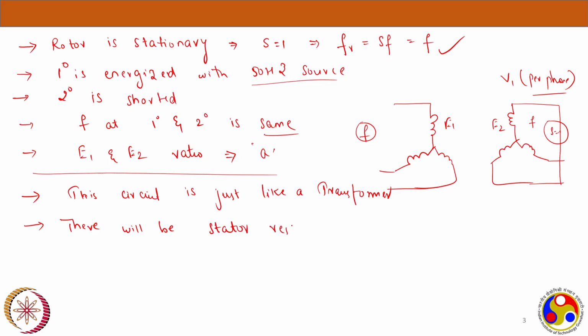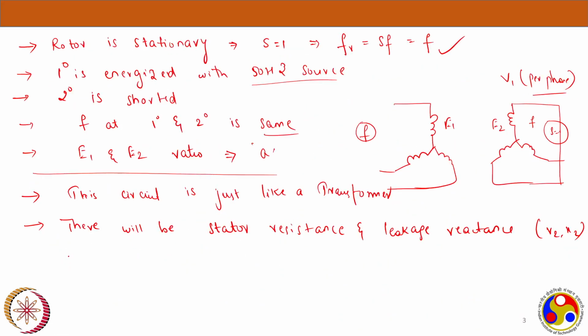Stator resistances and leakage reactance, R2, X2, and there will be magnetizing inductance. You know the importance of magnetizing inductance, right? We'll be discussing this in this session: Xm, which is much higher than R1 and X1. The reason we will also discuss.